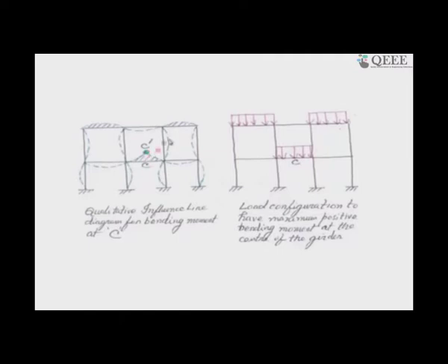So, to have the maximum positive bending moment here, I must load the portions which are shaded between this deformed curve and the original curve, and that is what has been drawn here. Loading any other place will effectively reduce the bending moment if there is a curvature present there. So, that's how it is. Now, suppose by chance there is an extension of this frame where the moment is released by internal hinges, then loading in this section will not affect this. So, that's what we have drawn.